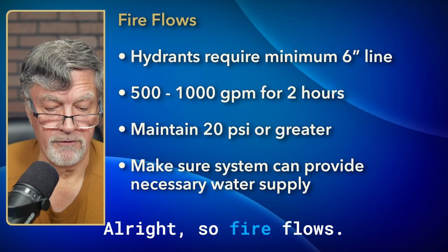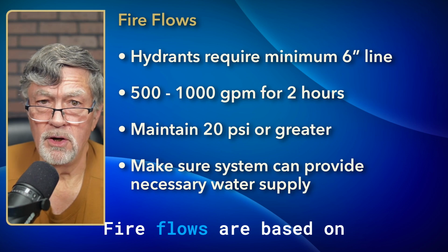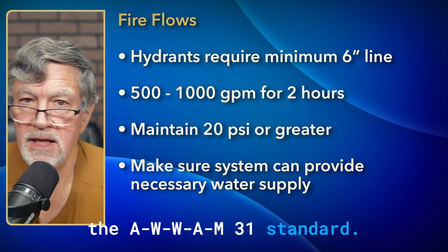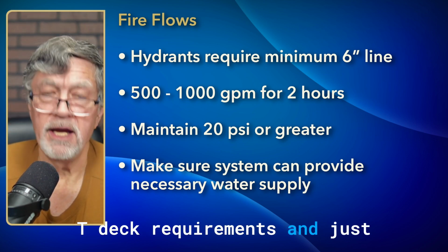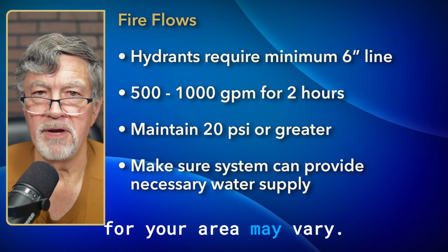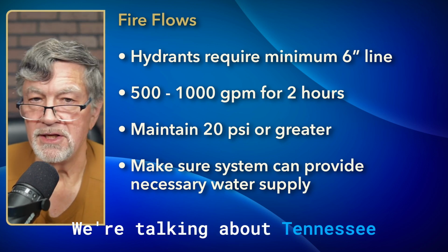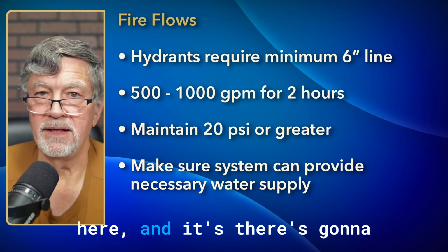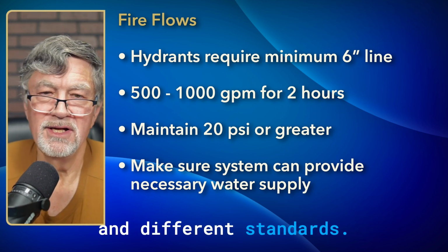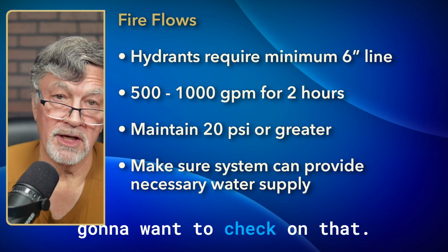All right, so fire flows. Fire flows are based on the AWWA M31 standard and TDEC requirements. And just a reminder that requirements for your area may vary. We're talking about Tennessee here, and there are going to be different fire flow requirements and standards around the country, so you're going to want to check on that.